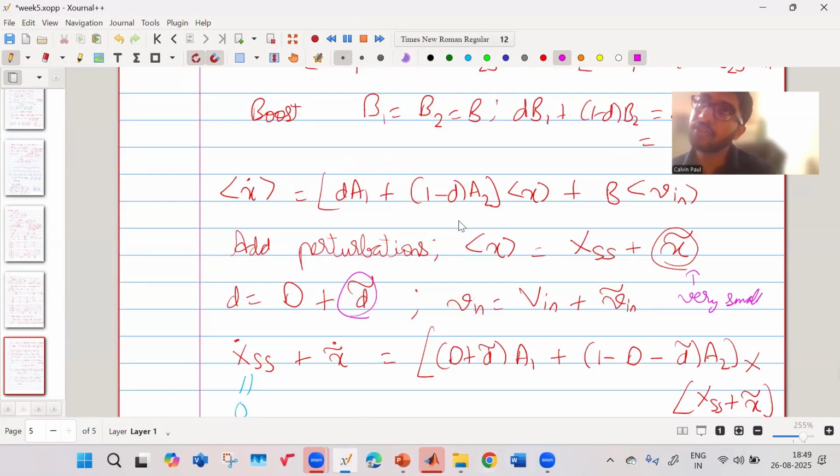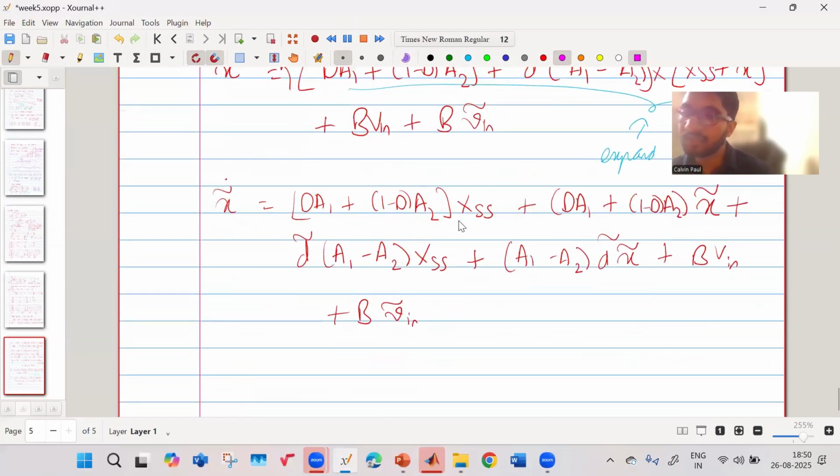But if you multiply 2 with 2, you get 4, or you multiply 10 into 10, you get 100. So in our case, we are considering those perturbations are very small, then negligible as compared to our main DC operating point. That is why we are ignoring the product of those perturbations. So we ignore this. Okay, we have ignored this. Very good. It's made our life simple. We don't want to complicate our life.